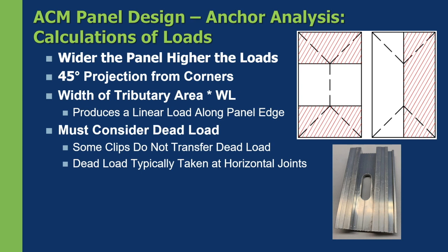This is a very good time to talk about dead load. Let your engineer know what clips you're using. Detail them clearly in your shop drawings, because not all clips are made equal. And the clip shown below has a slotted connection.